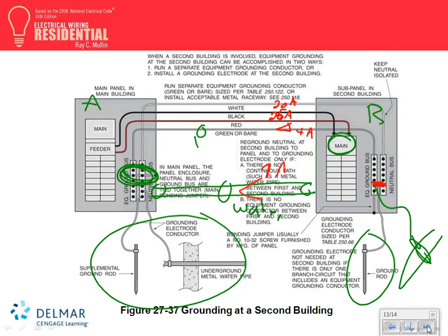Now you start heating your water, literally heating your water. There's 1 amp going through the copper pipe, because remember, the copper here is bonded to the neutral right here. So this is another neutral. That's the main reason why they don't want you to bond on the second building. Because if you bond on both buildings, the neutral and the ground are in parallel, so the neutral current can take any path that it wants.